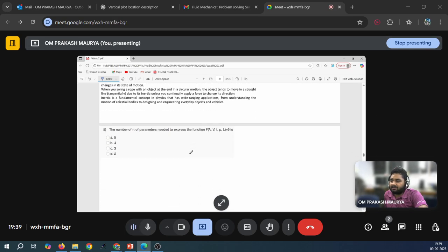Okay, so another question is question number 5. The number of pi parameters needed to express the function. You have these variables: area, velocity, time, dynamic viscosity, length.